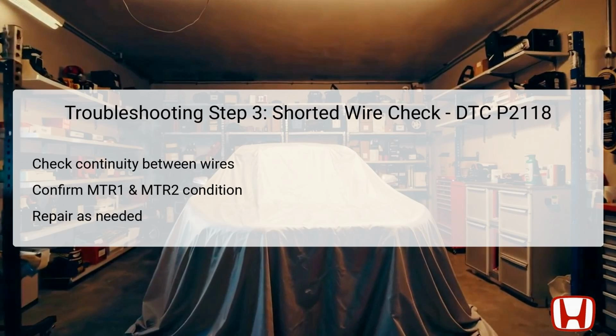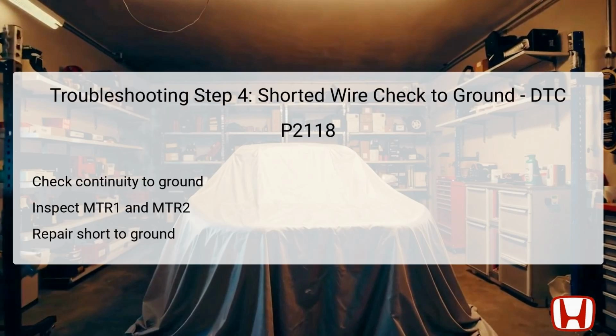If a short exists, it is necessary to address and repair this short in the wiring between the throttle body and the PCM. Once repairs are completed, you will want to verify that the functionality has been restored to the system. As we arrive at step 4, the next task is to check for continuity to ground in the MTR1